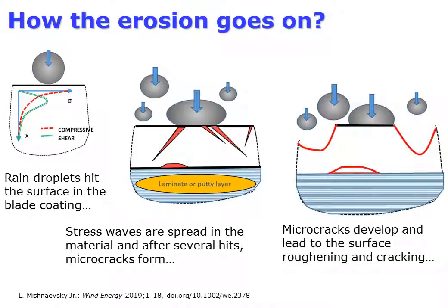How does the leading-edge erosion of wind turbine blades take place? Blades are rotating with high velocity under rain, hail, sun. Droplets hit the leading edge with velocity from 50 meters per second and higher. Day after day, year after year. Stress waves from these small impacts, propagating through the blade materials, are reflected on interfaces. The waves interact with inclusions and other materials. Polymer chains in the blade material are compressed and deformed.